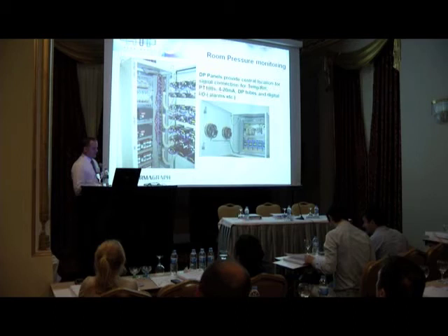So, as previously stated, it's all very well monitoring all of this data, but if there's a problem, you need to know about it. So what you need is some kind of alarm indication. We do that via either a traffic light beacon stack, which you've probably seen, what we call an alarm message display, which we touched on briefly, via volt-free contact, the BMS, which is okay, but once you've got one alarm, that's it. It masks all other alarms. You can do it via a network, something like email, or via SMS pager and text messages from mobile phone.